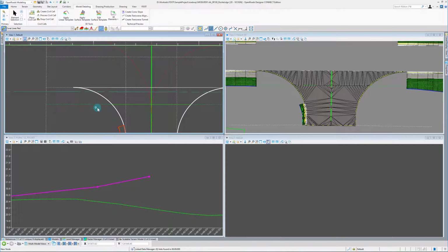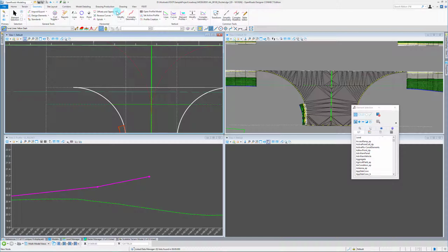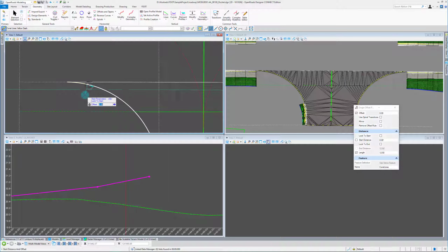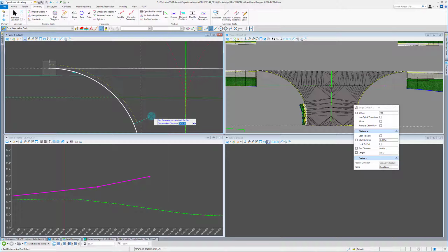Now most of these curb ramps are based on the length along the curb back. So what I'm going to do here is start drawing construction lines, yellow dash, since curb's usually drawn in yellow. And I have F curb here, so I'm going to make sure I have a 2-foot offset. I'm going to start from the end of this line, and I want to make sure this goes a little bit down the return, because what I'm going to end up setting up here is the distances to the next curb return as well, so I want to make sure I can at least get down there.